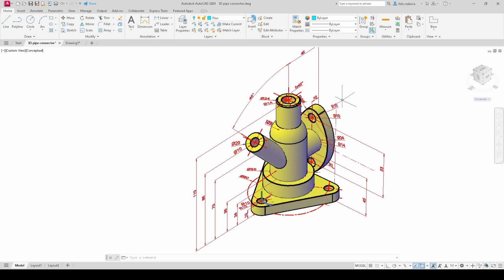The only difference is that this has already been, the diameter cylinder of 14 was already subtracted from the other cylinders, but we have to make sure that the inside geometry remains in place in this case until the very end, when we have everything on the proper layers, because here we have to do with intersections of cylinders, and if we extrude these before they should be extruded, or rather subtract these, the intersections will not align properly and will not really generate the proper curvature inside of the part.